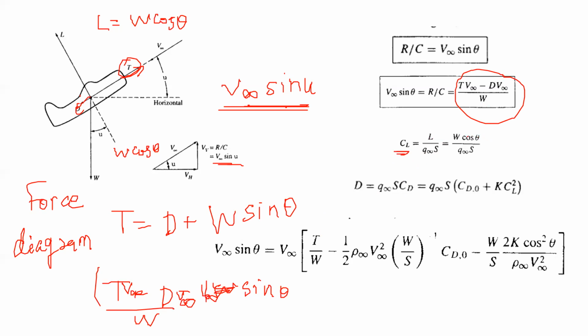So this is the lift formula, and q infinity is the dynamic pressure, half rho V squared. And this is the CL, and the formula for drag is from the drag polar, and we can arrive at this expression for the drag when you substitute the value of CL in this equation for the drag.